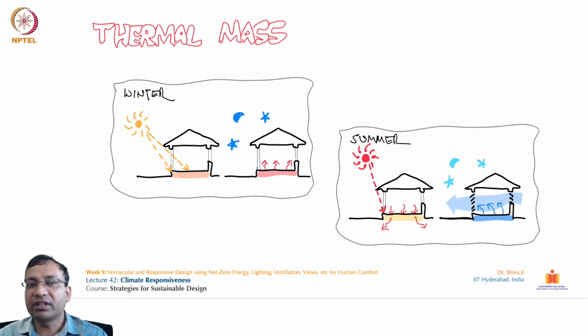So when we have a requirement of thermal mass, maybe we can go for these materials from the top: water, granite, concrete, sandstone, and clay tiles, etc. Where we do not want it, maybe in those places we can go from the bottom up. So these aerated or autoclaved concrete, you can see AAC blocks over here, has a 550 kilojoules per cubic meter Kelvin thermal mass storage capacity.